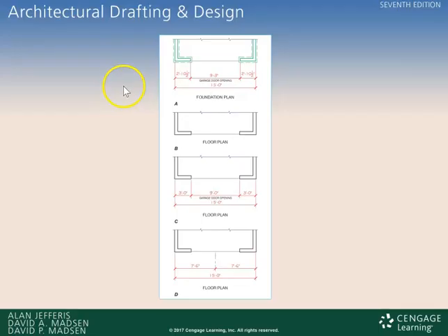You can, they say never to dimension twice on a floor plan, but in construction, unlike mechanical drafting, sometimes it's a good idea to help people out by adding a duplicate dimension in another location to illustrate your point.